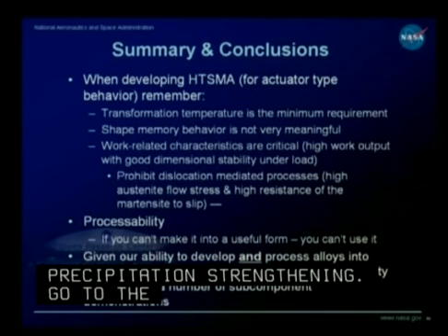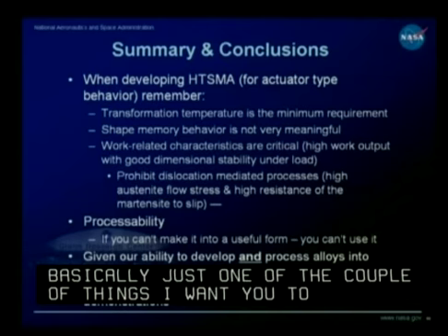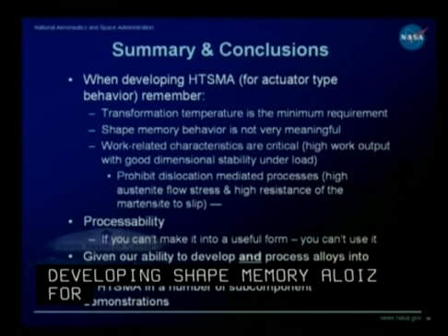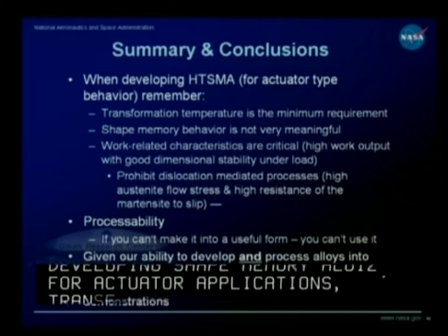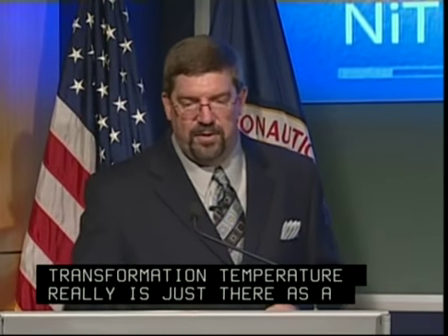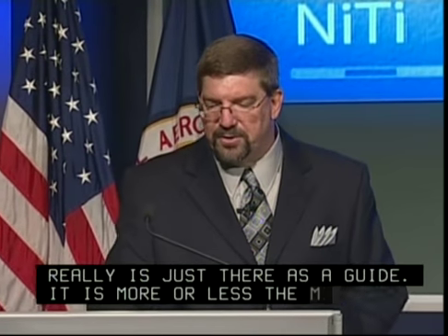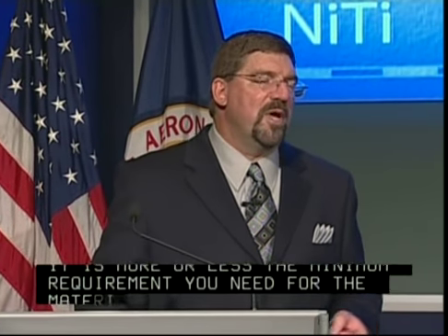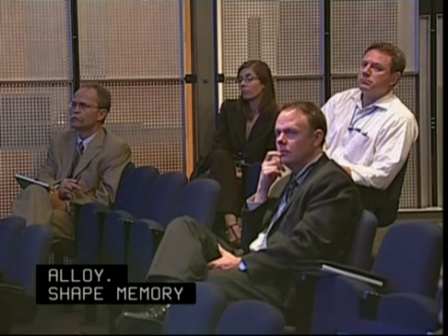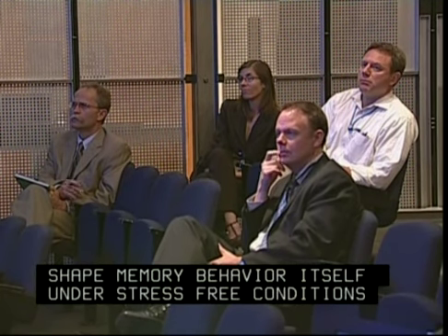Basically, one of the couple of things I want you to remember from this talk is that when developing shape memory alloys for actuator applications, transformation temperature really is just there as a guide. It's more or less the minimum requirement that you need for the materials if you want to develop a high temperature shape memory alloy. Shape memory behavior itself under stress-free conditions is absolutely meaningless. Unfortunately, that's what 95% of the people out there measure.